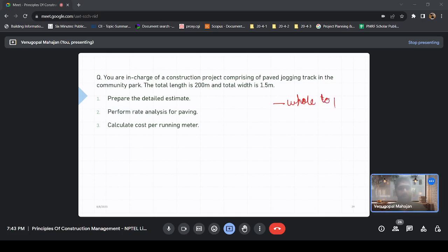There are two parts, which is similar to surveying. Wherever you go for estimating, you move from bigger portions to smaller portions. Then keep check of units. If something is supposed to be in SQM, you calculate it in SQM. If it is supposed to be running meter, you calculate it in running meter. And there is one more thing that is not discussed in detail, that is significant digits.